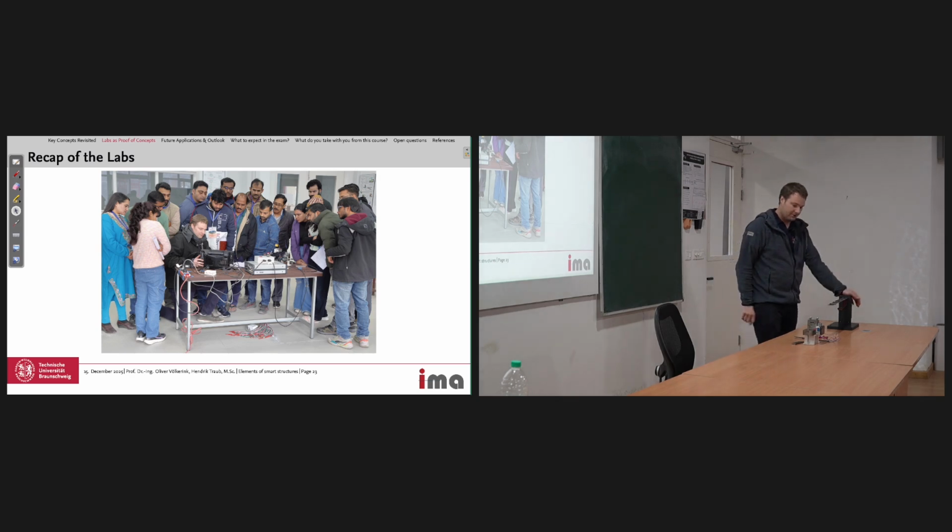first of all determined the eigenfrequencies, the first two eigenfrequencies of this beam. By the way, you can calculate them as well. But today we determined them experimentally, and we took the measurement of the displacement here and determined the frequencies. And after that, we did not, but we tried to get the mode shapes by determining the displacement at several points along the length. Okay?